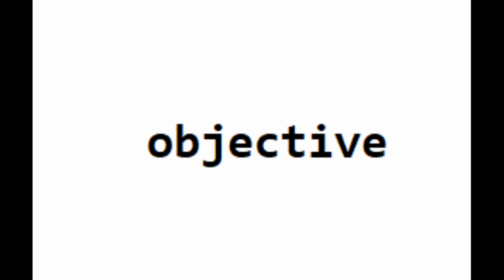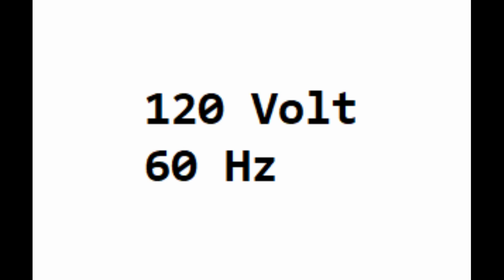A full wave rectifier is to be designed to produce a peak output voltage of 5 volts and deliver 1 amp to the load, and produce an output ripple of not more than 3%. An input line voltage of 120 volts at 60 Hz is available. A full wave bridge rectifier will be used.